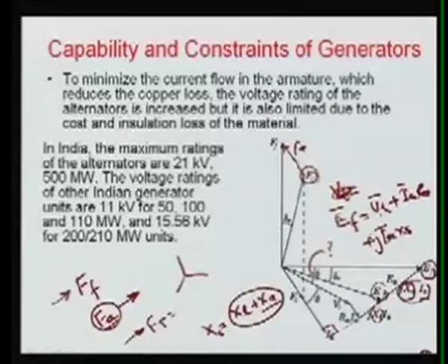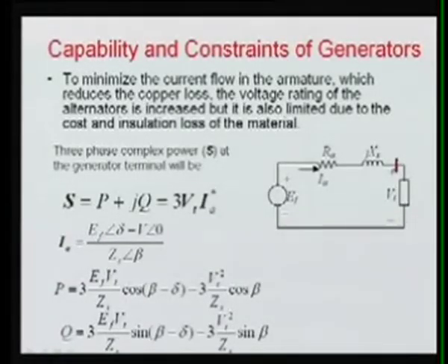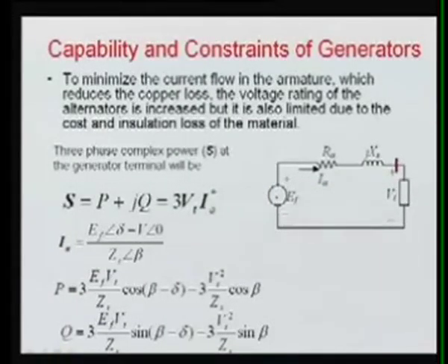Now this terminal voltage, that is the voltage of your alternator, which can be seen here, this is your terminal voltage of alternator. So the reactances and EF just we have written, this is your equivalent diagram of an alternator. Now this whole rotating mass can be represented by this equivalent electrical circuit, where this E is the field EMF, that again depends upon the field excitation level, then this current IA, that is your armature current, and it is flowing through the winding resistance, and this XS has two components. One is the leakage, this actual inductance of the coil, and due to this armature reaction component, so it is called synchronous reactance. And this is your terminal voltage, and then we have, let's suppose, one load, and load it may be here the transmission lines, those are carrying power.